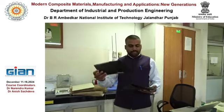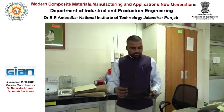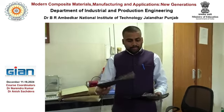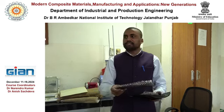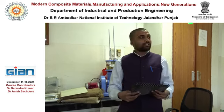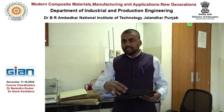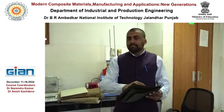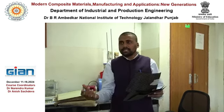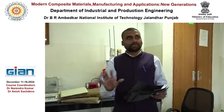So this is the carbon fabric. This is the 12K carbon yarn fabric. And here also you can produce laminates based on your requirement, right? You can arrange these layers at different angles based on the properties required in that particular direction. Because one important thing here is that textile materials are anisotropic in nature. You know that, right? You have some properties in 0 and 90 degrees, and at the bias angle you will have different properties. So this is anisotropic, and our composite material, that is textile reinforced composite material, is also anisotropic.